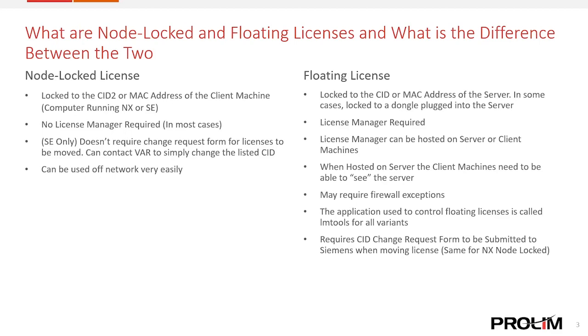But generally, if you're on a server that has all those different CAD software LM Tools on it, my recommendation is to have an LM Tools shortcut for each individual one. So I have an LM Tools shortcut for my Solid Edge license manager, where it is installed, and a shortcut for my Siemens PLM license server, which would be the NX LM Tools. That way I have separation, right?